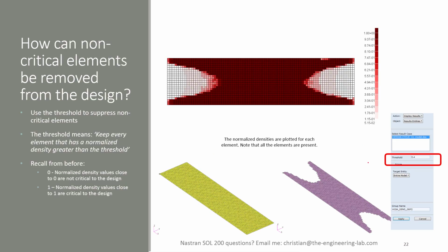And then here, if you want to know how to see the optimization solution, again, you open Patran, you specify the threshold. Here, the threshold is 0.4. So here we are saying that anything above a value of 0.4, so that's around here, everything here is to be capped. And everything less than 0.4, that means you ignore.